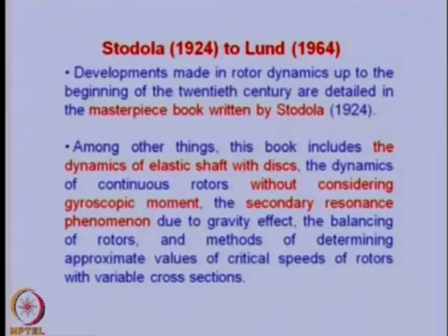In this second phase, I will be starting from Stodola, from 1924 to Lund up to 1964. The development made in rotor dynamics up to the beginning of the 20th century is detailed in the masterpiece book written by Stodola. Among other things, his book includes the dynamics of elastic shaft with discs, the dynamics of continuous rotor without considering gyroscopic moment, the secondary resonance phenomena due to gravity effect, the balancing of rotors, which is of very much practical importance, and methods of determining approximate values of critical speed of rotors with variable cross sections.